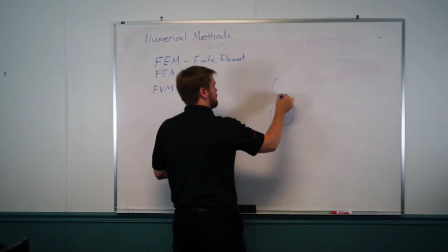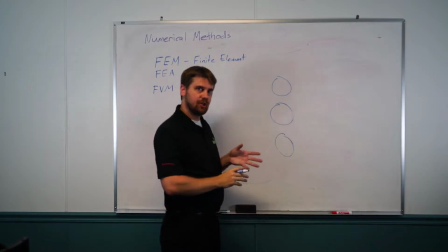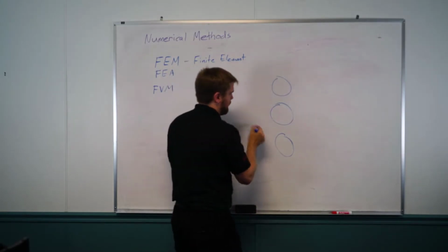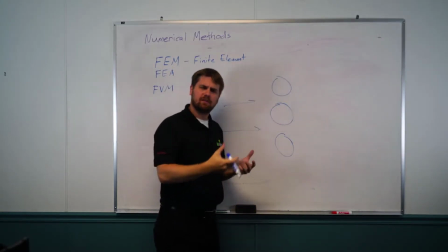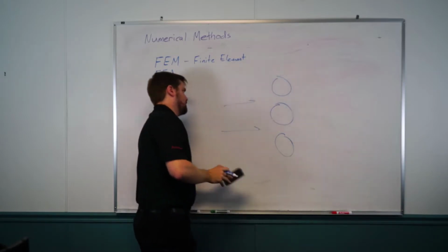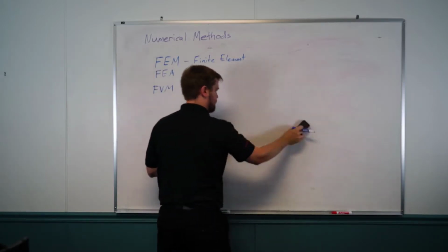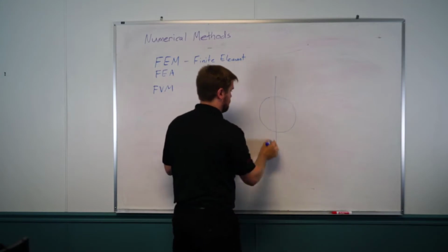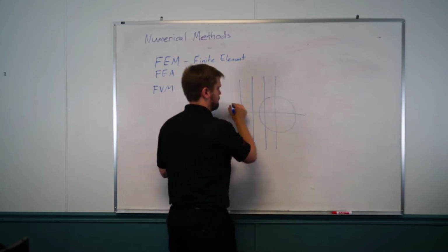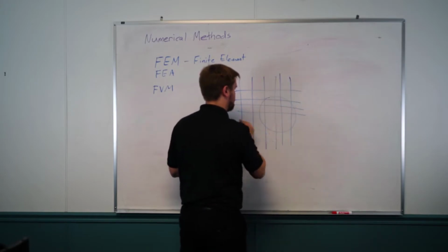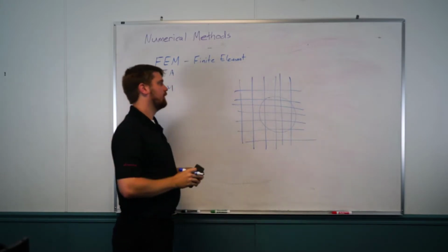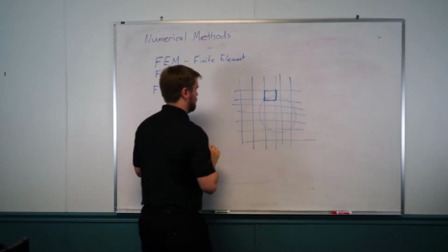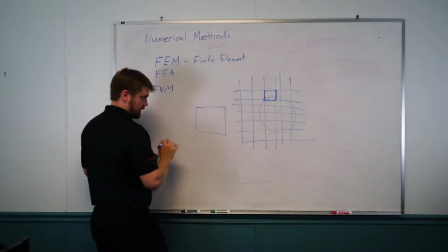The basic idea behind it is, let's take this example. Let's say it's a heat exchanger and there's fluid flowing in and out of the board through a series of tubes. And let's say there's air flowing in between these tubes. Think of it kind of like a radiator. If we take a look at just one of these tubes, the mesh that our SOLIDWORKS flow simulation tool might use looks something like this. A Cartesian grid. And if we take a look at one of these elements, let me zoom in on maybe, let's pick one, how about this guy? It looks kind of like this.